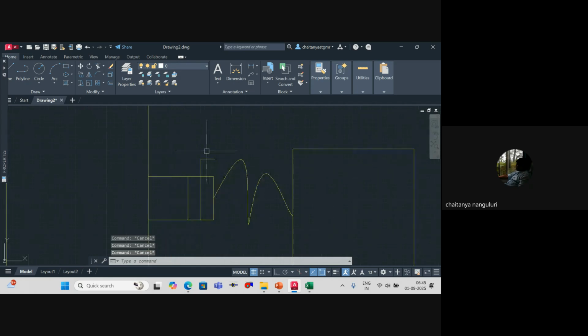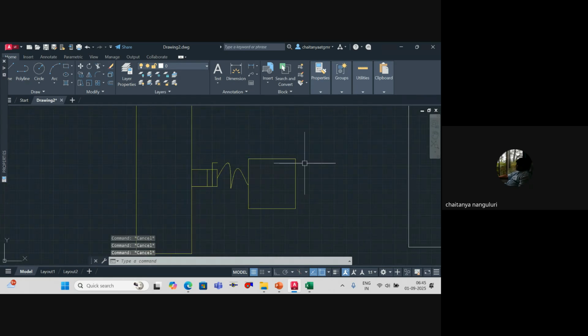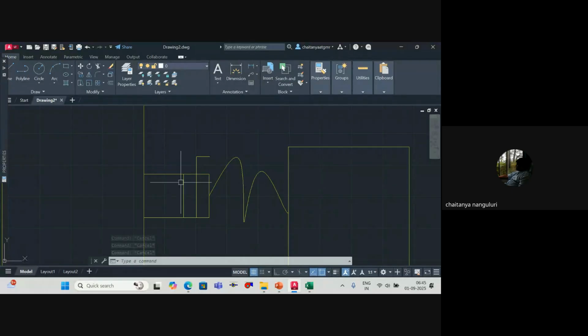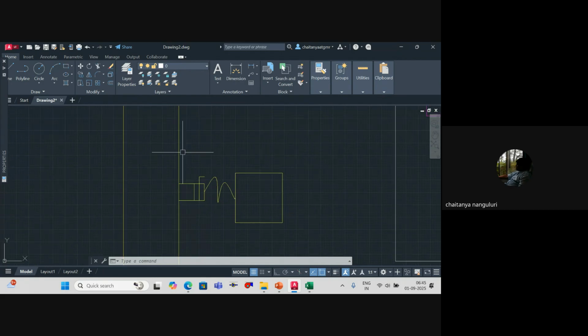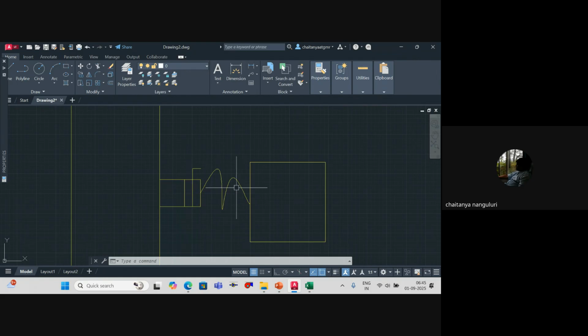So at these locations, to control the volume of air per individual air terminal, you will go for this butterfly damper or the Spigot damper. You can call it a butterfly damper or a Spigot damper. Am I clear? So that even connects between your main duct and your flexible duct as well. Got it?